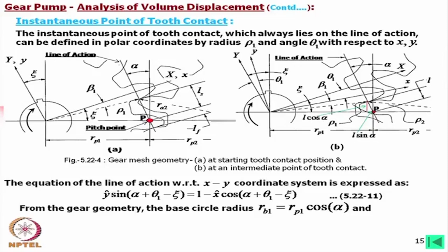This means that while you are going for this analysis, you have to know what center distance they have made and the gear correction if produced, and from there we have to find the actual working pressure angle that we can put. But normally, in the case of gear pumps, we do not change the center distance. So, even if corrections are introduced there, the alpha remains constant, that is, remains the standard one.